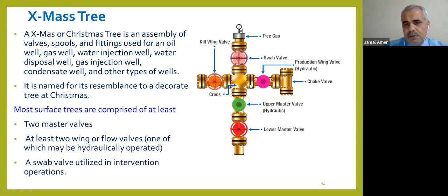Even when we use the same gasket many times, it's a potential source of leak. If any leak started in one flange and action wasn't taken immediately, this leak will become worse, because after some period of time it will create corrosion on the internal face of the flanges. However much you tighten the bolts, you cannot fix this leak until you replace the whole valve or choke.